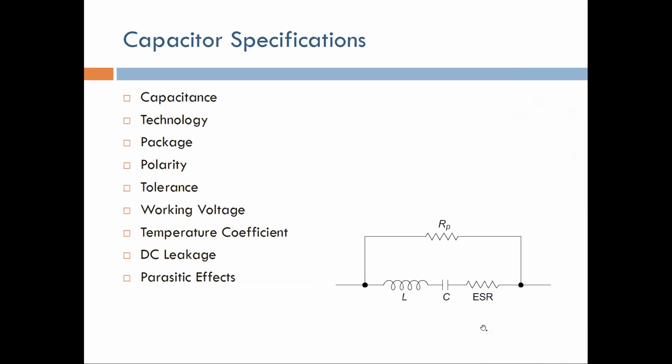There are several types, and each one of them has certain advantages and disadvantages. Sometimes it's the price, sometimes it's a particular application, sometimes it's the parasitic effects that are present inside. Sometimes it's the kind of capacitance value you can get from these technologies. Sometimes it's the maximum voltage, the rated voltage. Sometimes you need capacitors with a rated voltage of a few kilovolts, for example. Sometimes you can get that from particular types of capacitors, not the others.